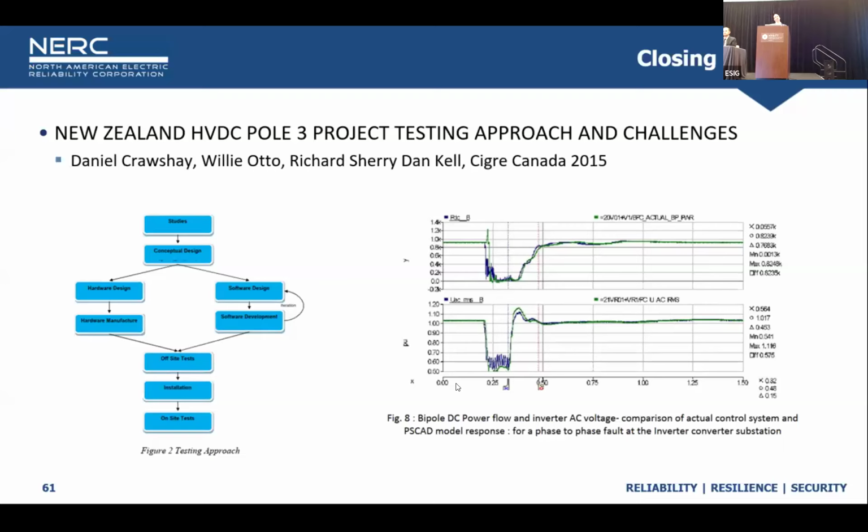So right now it's actually easy. We just do a direct compile DLL and we can wrap it and we can run it in PSCAD. This was before we had the ability to do this. This was what we were doing back in, again, 2015, looking at how we can make sure that HVDC, the original inverter-based resource, can get integrated into the grid and maintain stability on everything we need to do here.